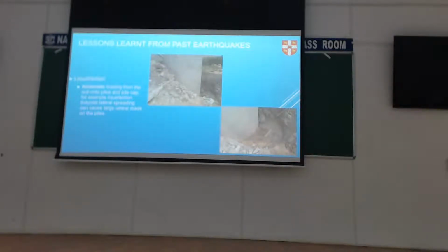And the way it shows that is you can see how much the ground moved here. That's about three quarters of a meter. And if you look carefully, you can see this soil piling up behind the pier as well. And these piers were supported on a single pile below. And again, that's a bad idea. And obviously, they have seen huge amounts of lateral loading because of the laterally spreading soil.